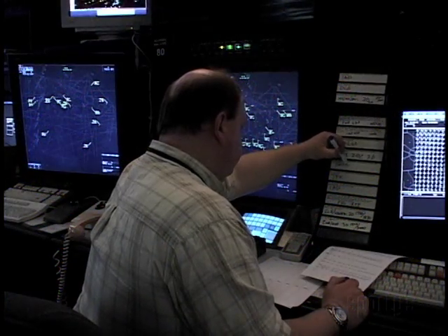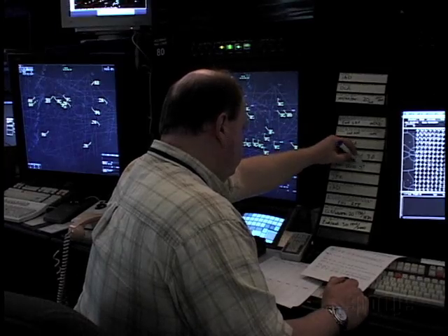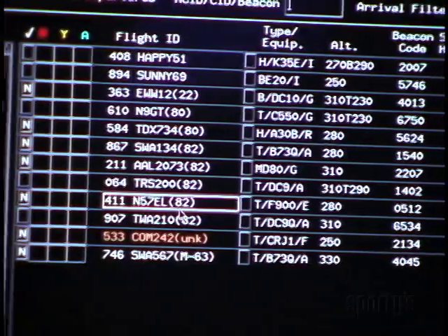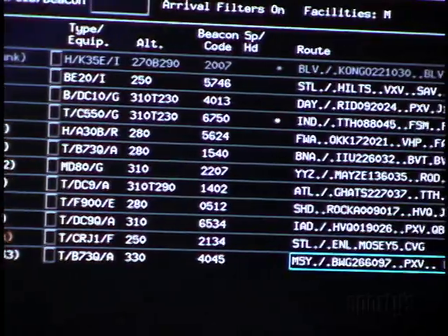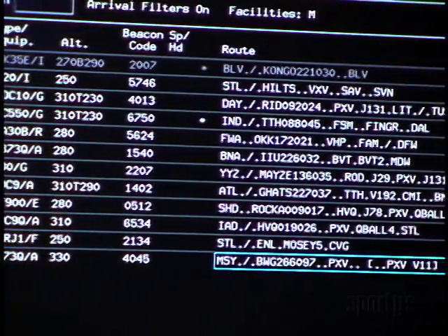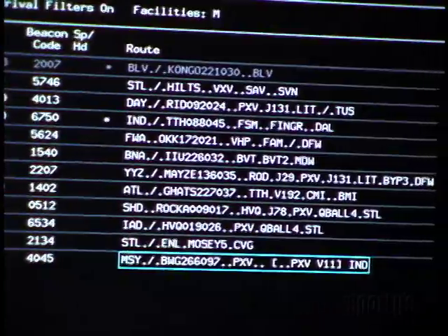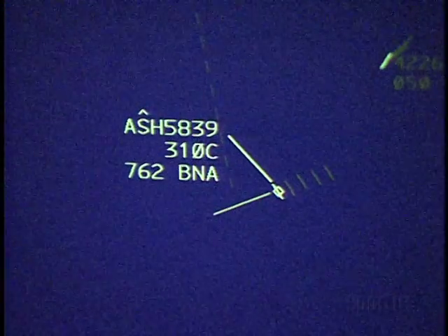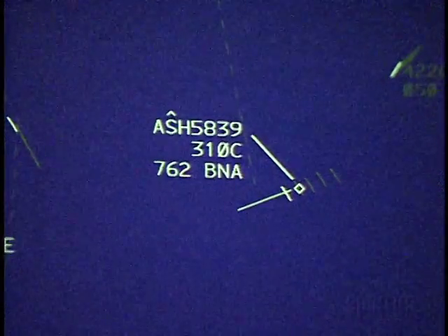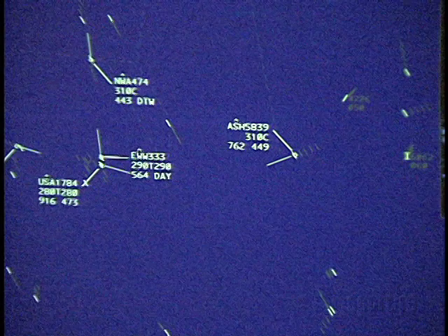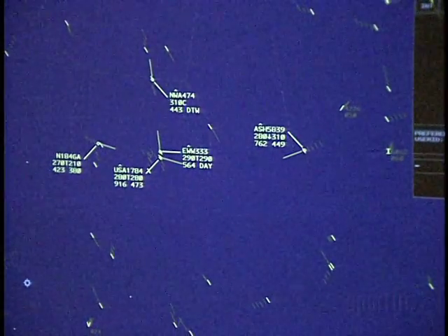Flight strips used to be printed out and still are at some facilities. The centers now have electronic flight strips that contain the same basic information about the flight and where it's going. These get to the appropriate controller well in advance of our arrival in his airspace. Another way the controller helps watch out for us comes from our Mode C altitude readout. The controller can see how high we are in relation to terrain and to other aircraft.